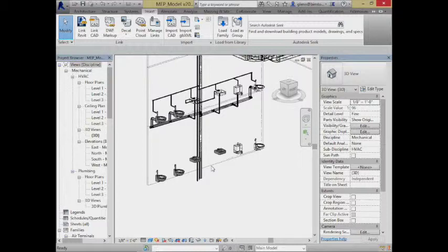Now, we have the whole issue of the sanitary waste. Let's think about the other things that are hanging around in here. For these different fixtures in the bathroom, who needs hot water? Pretty much only the sink. So this is going to have some sort of hot in. We'll have to supply something there. It's typically a 1/2 inch line, but it could be a 1 inch line. It really just depends on how much flow you have, how much pressure you have in the system.